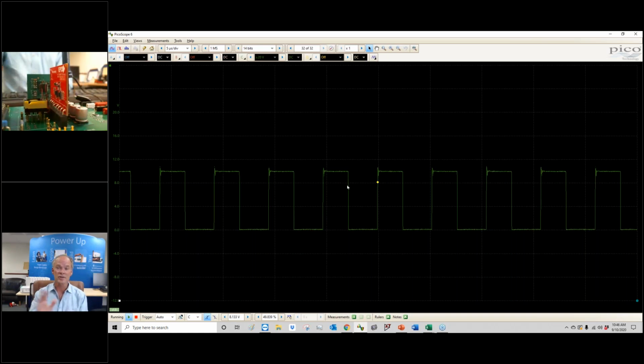Now we're going to send this in to drive some GaN devices. So we've got to divide that 10 volts down to work. I think we've got TI drivers on the board to drive the GaN. But we see it's just a little bit slower than 200 kilohertz here. But our design processes always allow for some margin on frequency to make sure that's okay.